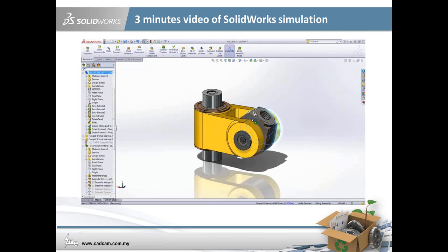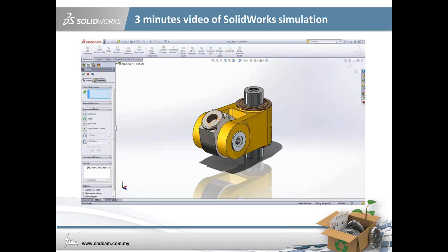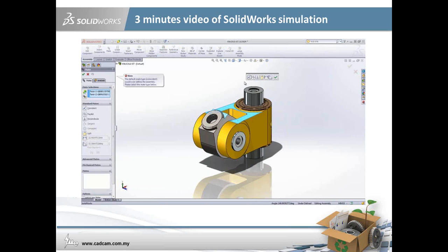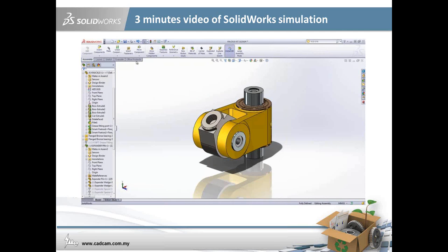Let's center the rod eye up with a width mate and then locate it in what will probably be the most extreme loading situation. Notice that when I add a mate between these two faces, SolidWorks warns me that the default coincident mate will not work. So we'll choose an angle mate and place it at 35 degrees. Looks perfect.